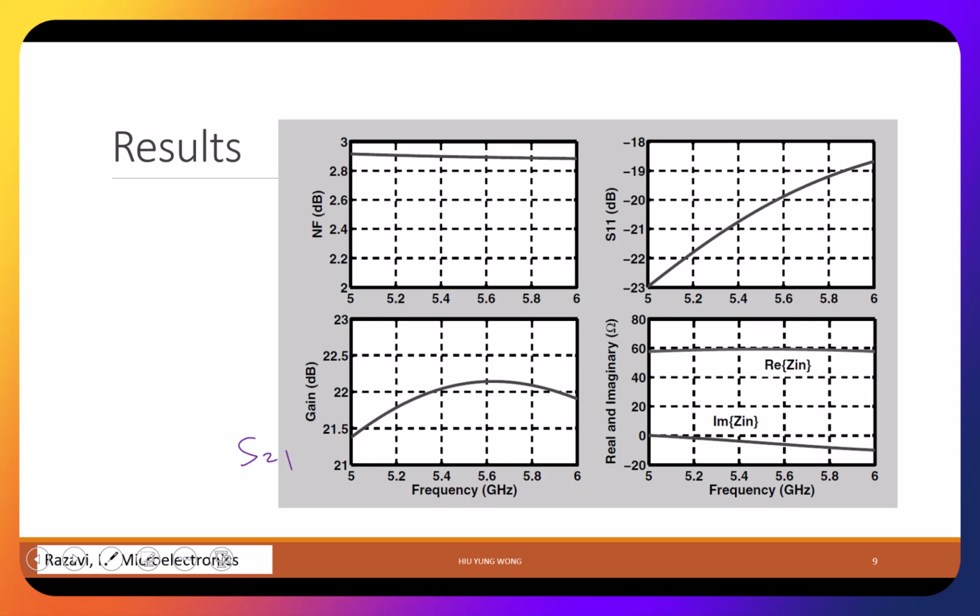If you have a rather lousy layout, maybe I'm still okay. But do not have the metal wire going around the world and then coming back, right? At least you need to make it a little bit closer. But I'm not checking whether this should go with a minimum distance, or your wire is not wide enough so you have a large resistance. I'm not going to do that. But just make a reasonable effort.